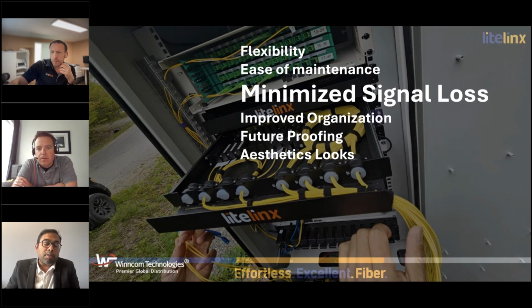Right. So when we were designing the solution, one of the things we liked about LiteLinx in this case is we can discuss with them exactly what we want. Because we understand the fiber characteristics and type of fiber we are using, we were able to design something which has the right type of bend radius. And if you bend the fiber more than you need to, or more than it's allowed to bend, it'll still work, but the degradation of the fiber will be more than what you expect.